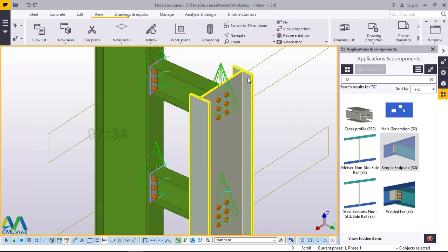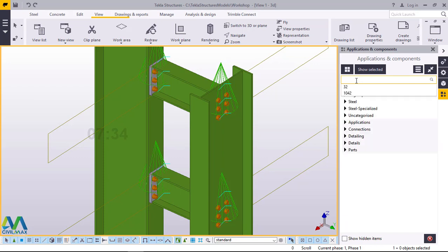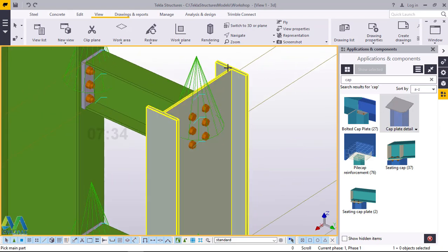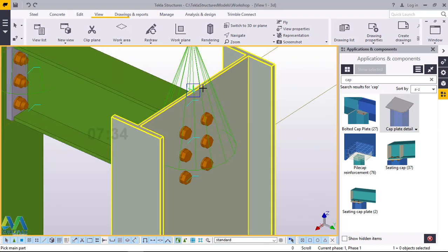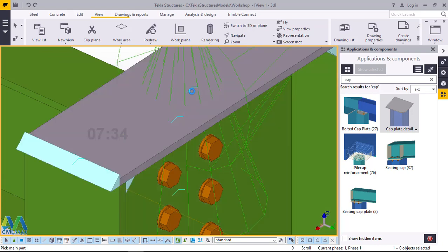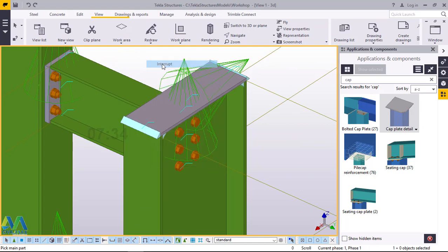Now our next move is to create a couplet for this beam, because we'll be placing this where our crane runway will be sitting. So we'll come to couplet here. We'll just type couplet. Pick on that, then pick on this column, pick the location, which will be in the middle of that column at the top.